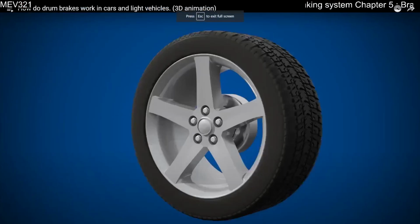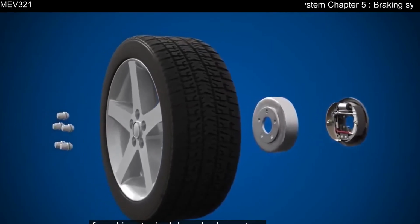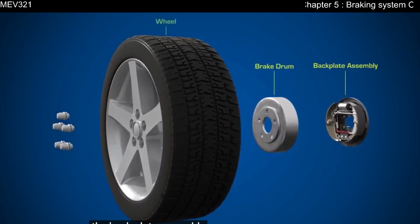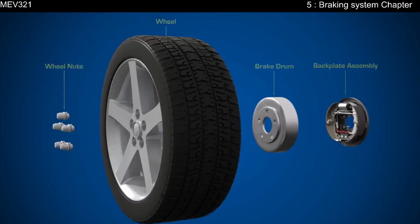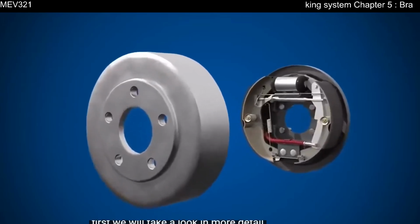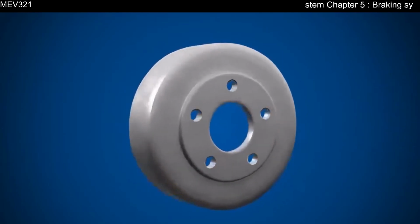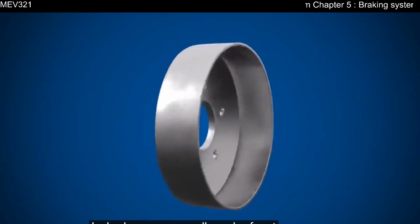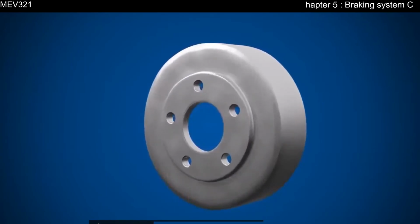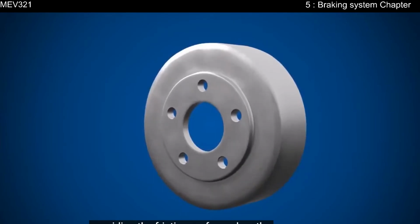Let's take a look at the components found in a typical drum brake system. We have the backplate assembly, the brake drum, the wheel, and the wheel nuts. First, we will take a look in more detail at the brake drum and backplate assembly. Brake drums are generally made of cast iron, which conducts heat well and is slow to wear. The drum rotates on the axle and wheels, providing the friction surface when the brakes are applied.